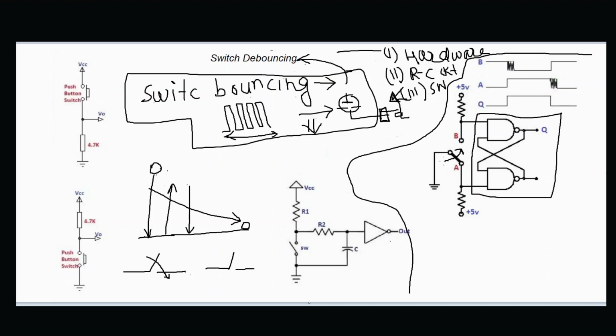So consider this schematic. So this is my logic 0. It is connected to ground, logic 0. So this is a NAND gate. It will become 1, right? And this is connected to a pull up. So this is 1, and then this is my feedback over here, this is 1, so this is a NAND gate, it becomes 0, right?